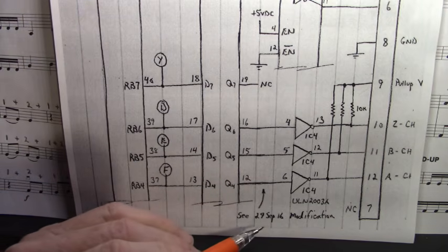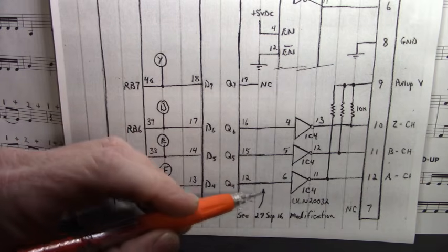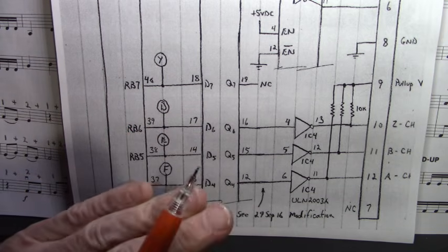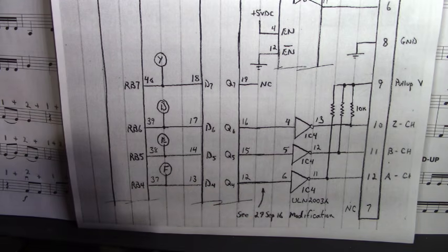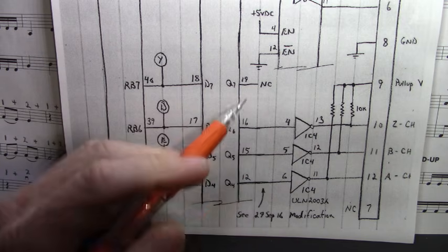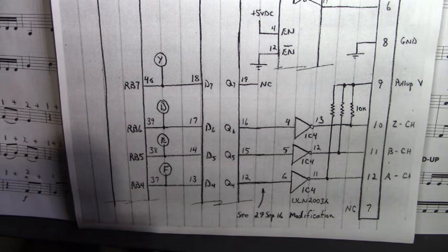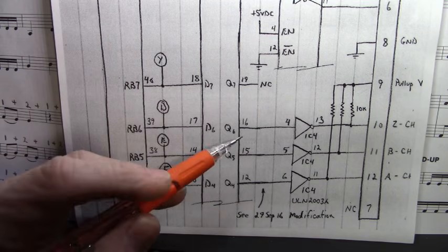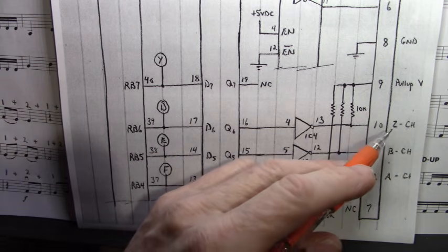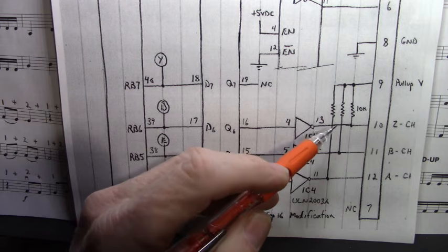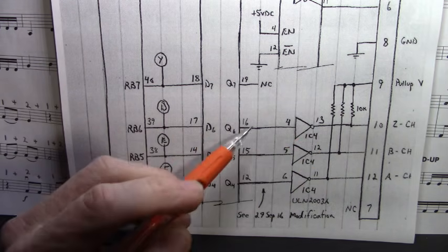Now on the 29th of September of 2016, I added a 7414 between the output of the 74HCT374 and the input of the ULN2003. I did that because on the Z pulse, without that inversion, prior to reaching the input of the ULN2003, the output was always high. Well, that's not how I wanted the output to be. I wanted it to be mostly low, and then when we had a Z pulse occurrence at pin 10, the Z channel output, it would go high and then low again. So I inverted it right here.